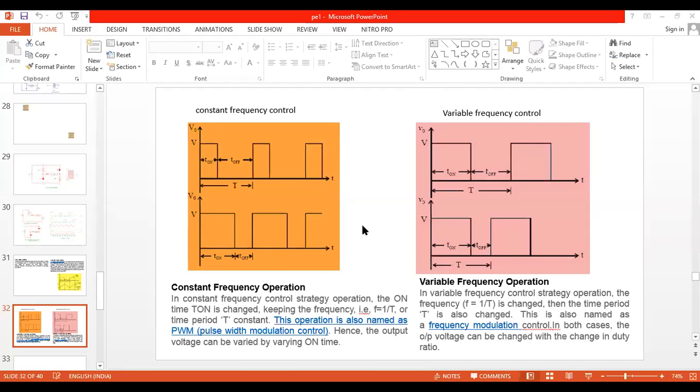That is, in our motors also, if I want to run the motor with high speed, what should be the frequency? Anyone tell me? Frequency should be low or high. Take an induction motor. I want to rotate the motor with high speed, so the frequency should be high. So when you change the frequency, the speed of the motor also starts to change.